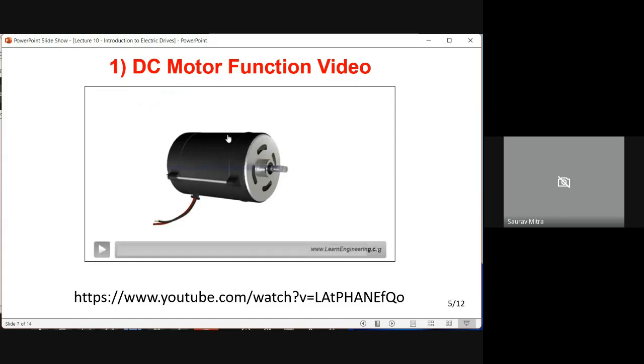They are placed in a magnetic field. That field is an electromagnet, because if you remove this source, the electromagnet will be disconnected from the source and the magnetism will not be there anymore. It will be a simple coil. Whenever this current carrying conductor is placed in a magnetic field, which is an electromagnet, the field is nothing but a magnetic field which produces flux or flux density. A current carrying conductor placed in a magnetic field experiences a force, and that force rotates this shaft.